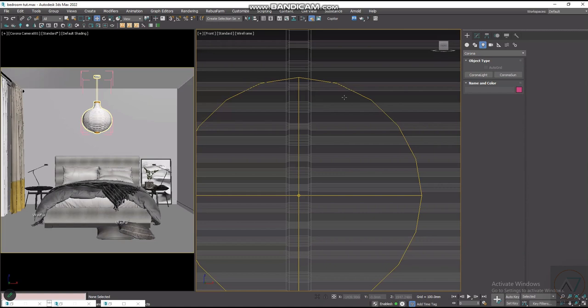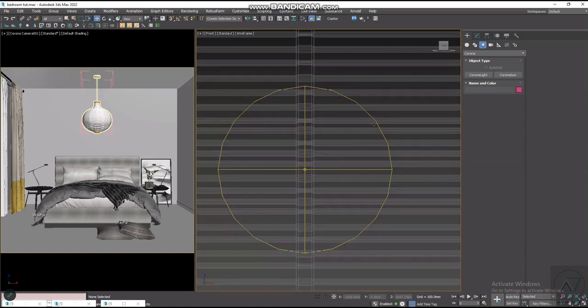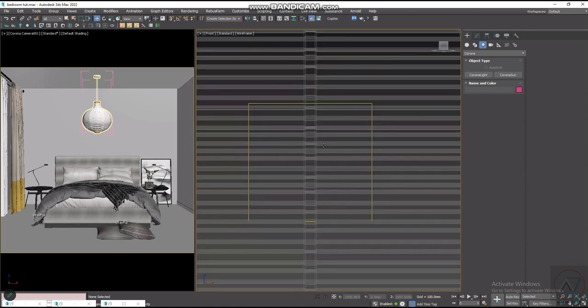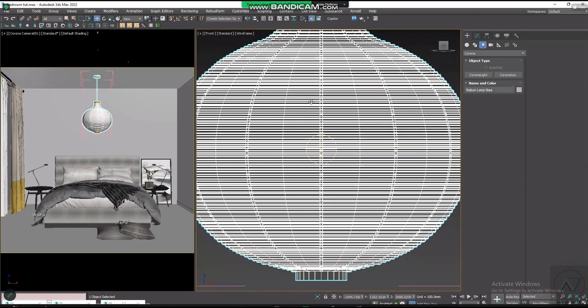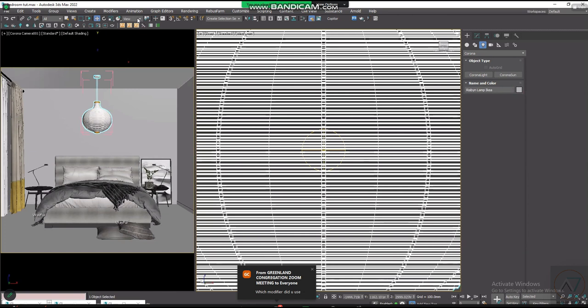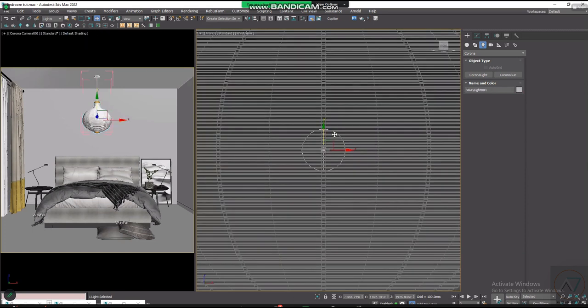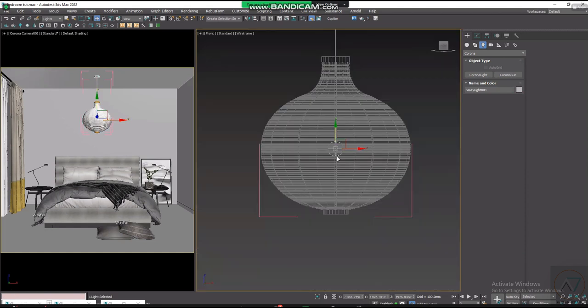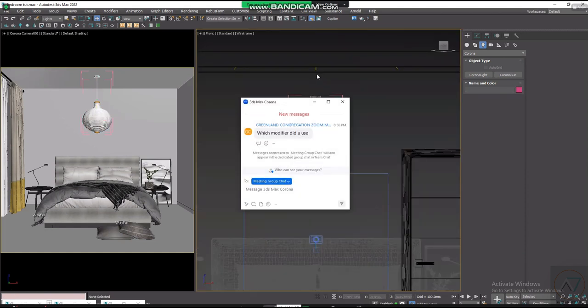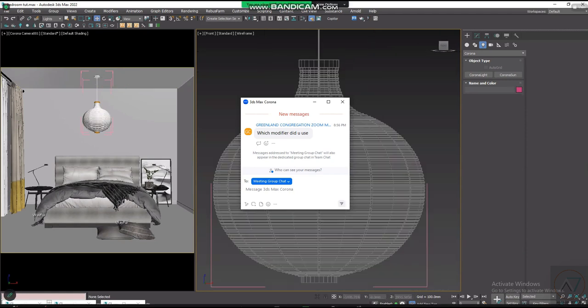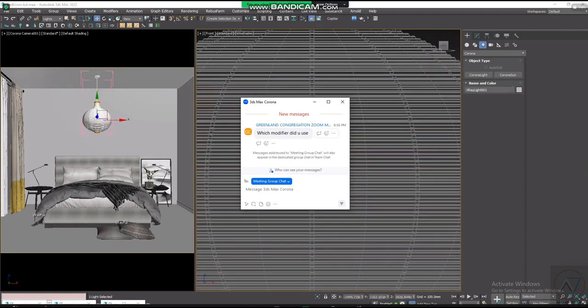I don't know. Let me try to select the light. It's a V-Ray light. So to change it to a Corona light, I want to draw. Okay, it's not selecting. There's another trick for you to be able to select. Just like you see this view here, oh, sorry, no, this one here, the selection filter. You can change it to light, meaning that you want to select only lights. You can see now anything else you click, it's not going to select. If I select a light, you can see this light we drew here is selected. So yeah, you can use that to select just lights.